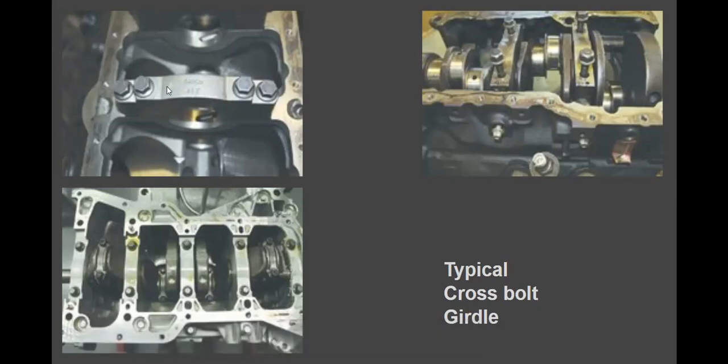they used to say, hey, it's got a 4-bolt main or 2-bolt main. So this being the main journal is where the crankshaft, it's the bore where the crankshaft rotates. So that bore is actually machined with those caps bolted in place, which means those caps are not interchangeable. So if I remove a cap, I have to put it on in the same location and the same orientation as when I removed it. This is one of the challenges with the traditional or typical style crankshaft journal, okay?